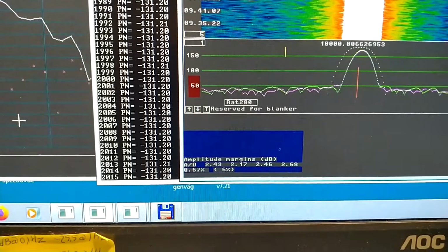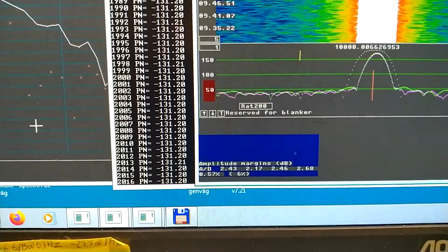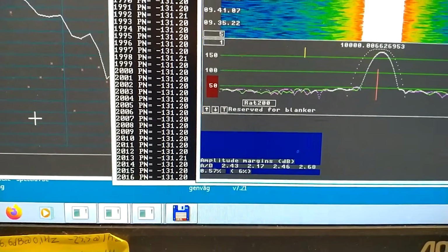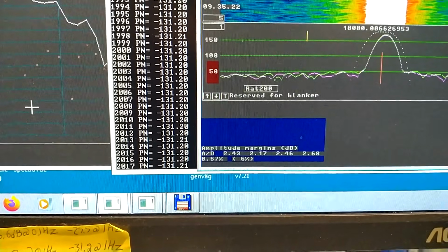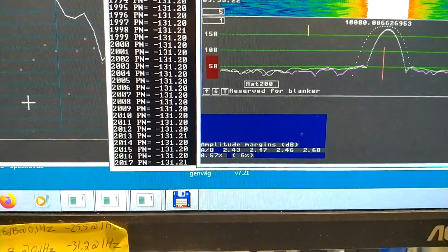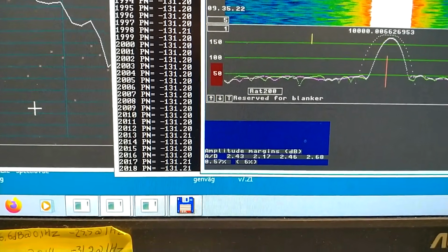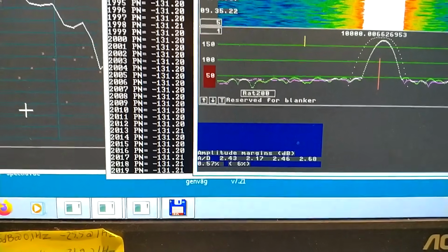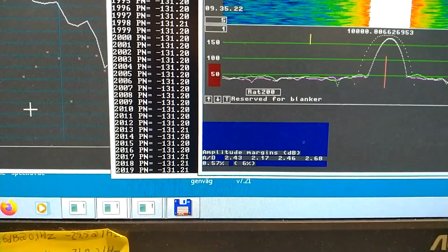Not very significant, but with these long waiting times, I think the value is fairly accurate. I will change to a current of 1.2 milliamp per crystal to get 100 microwatts power in each one. The resistance is about 70 ohms. And I think the performance will be somewhere in between.